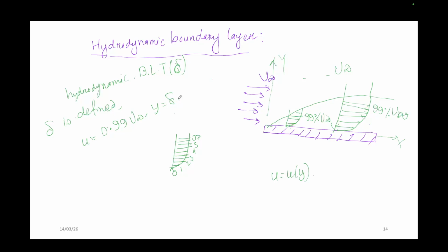And what is the reason behind this hydrodynamic boundary layer? It is because of the viscosity, which causes momentum diffusion from the wall into the fluid. That's why we get this hydrodynamic boundary layer condition. Okay. So this governing equation, just a minute.